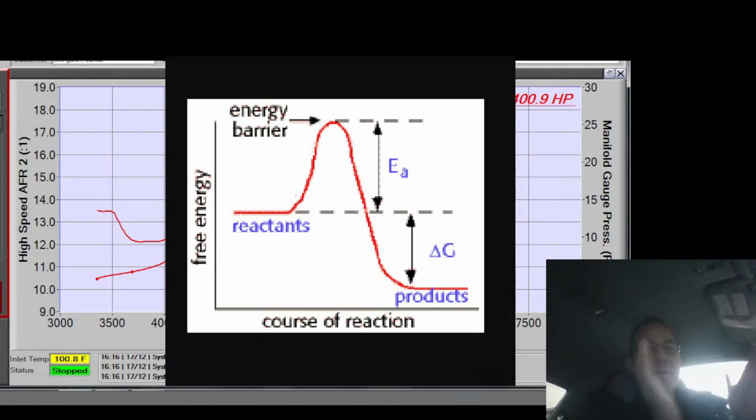Well, here I have a lot of energy traveling through two contacts in this gigantic breaker, and I pull it apart, right? There's going to be an arc. And so giant breakers have a bunch of things built into them to quench that arc. They have what's called arc chutes, a bunch of layers of melamine that are really close to the contacts. They just hug the outside contour of the contacts to prevent an arc from traveling around or out. So it gives it less pathway for the arc to travel.